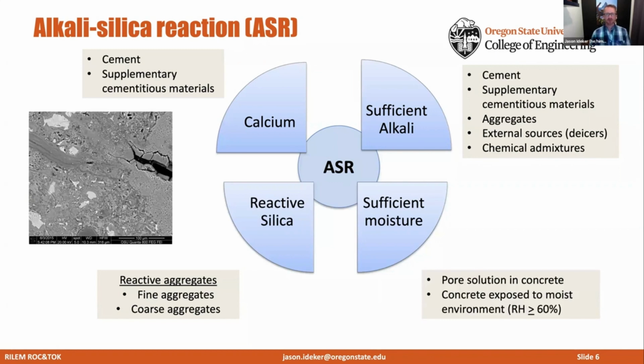And then you need sufficient moisture. So, hopefully we're all aware that there's pore solution inside concrete, and concrete that's exposed to a moist environment, something with a relative humidity greater than or equal to 60%, could be subject to ASR. So we generally don't think about ASR occurring in the interior of buildings, unless you maybe have a leak, something like a plumbing leak or a swimming pool, for instance. But generally, we're talking about concrete that's exposed to the environment. So dams, bridge decks, pavements, columns, those types of things that would be in exterior concrete.